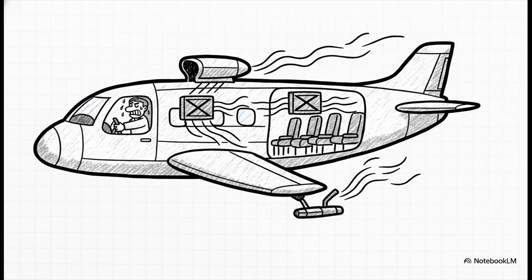In this extreme scenario, you rely entirely on emergency ram air ventilation. Outside air forcefully enters through the dorsal NACA vent, ventilates the cabin, and exhausts right out the forward safety valve. It keeps everyone breathing. But I want to leave you with this final thought.